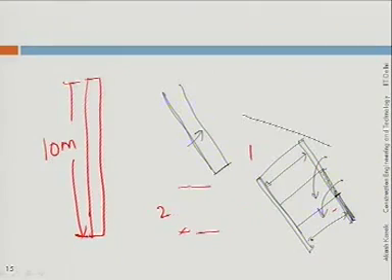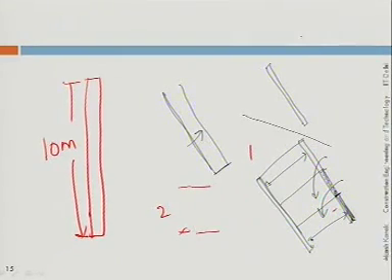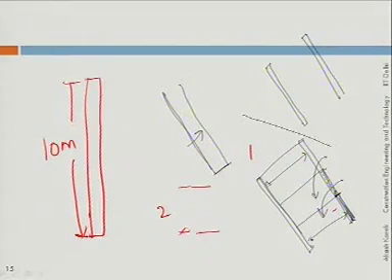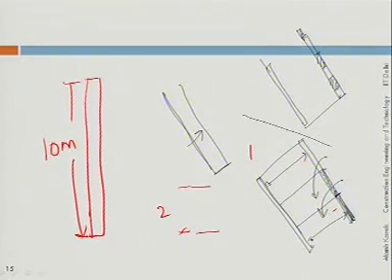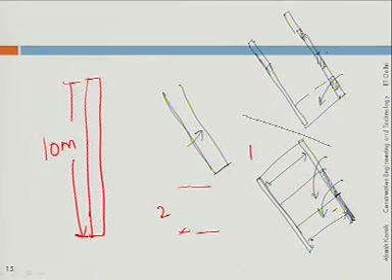There is another method also I will tell you, in which what you do is, this is the bottom shutter, the top shutter you put in one piece, but this top shutter will have some windows at appropriate locations. So, if you are pouring the concrete here, you will be using this window, then you will be using this window, then you will be using this window. Is this clear to you, technology class?